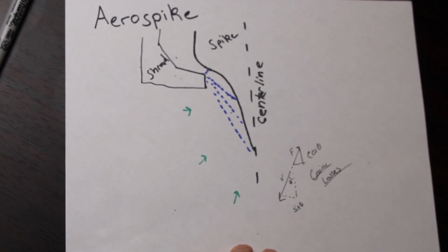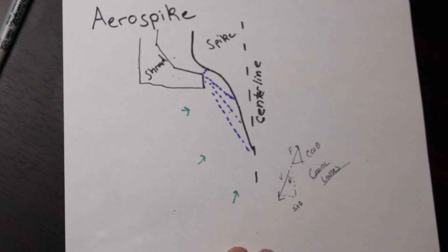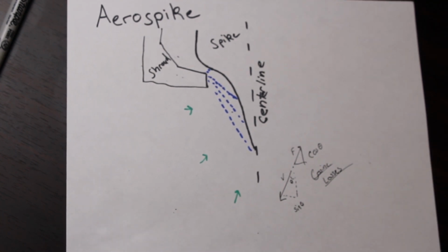Then we can use trigonometry to figure out what expansion angle from the Prandtl-Meyer function we talked about earlier gives us that, so that we can have the flow leave the spike in a perfectly axial direction. So we have to do the math now. This is the fun part. So let me start writing, and I'll be back with you in just 1 second.